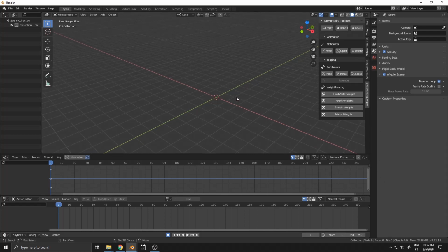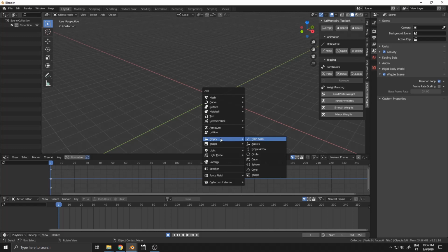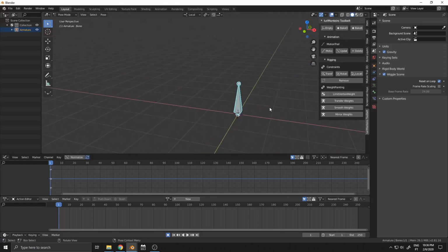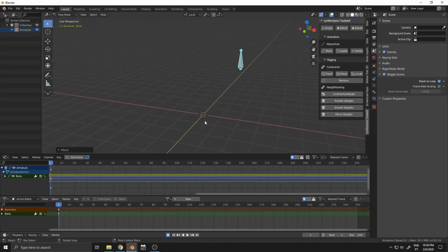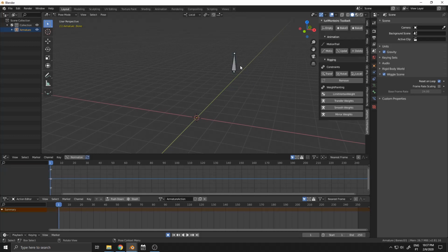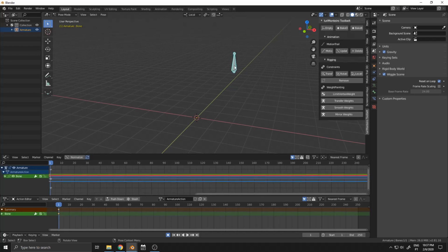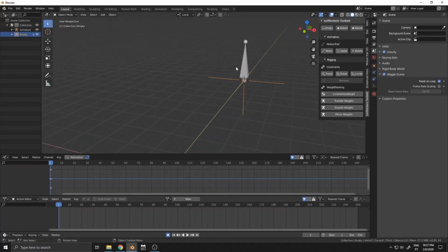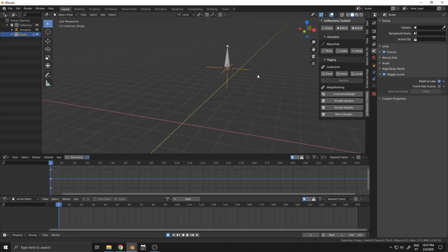So it's a tool that I use to simplify the clicks that we usually use in Blender, because we have to switch lots of modes and go into these panels and all of that. For example, imagine that this is a rig and you want to create a locator there. You select the bone, place the cursor there, and then if you create an empty, it's going to create an empty where the bone is.